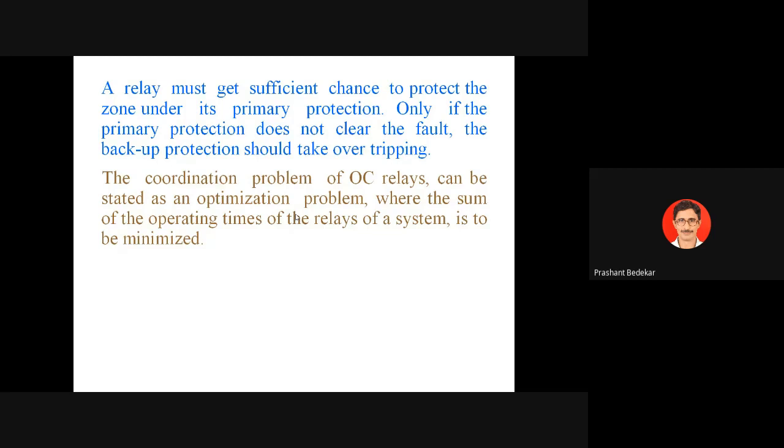Less is the time of operation of relay, less will be the time of operation of circuit breaker. That is, the fault will be cleared with higher speed and there will be less loss. So to avoid losses, to avoid power failure, there should be proper coordination. Time of operation of relay should be as minimum as possible.